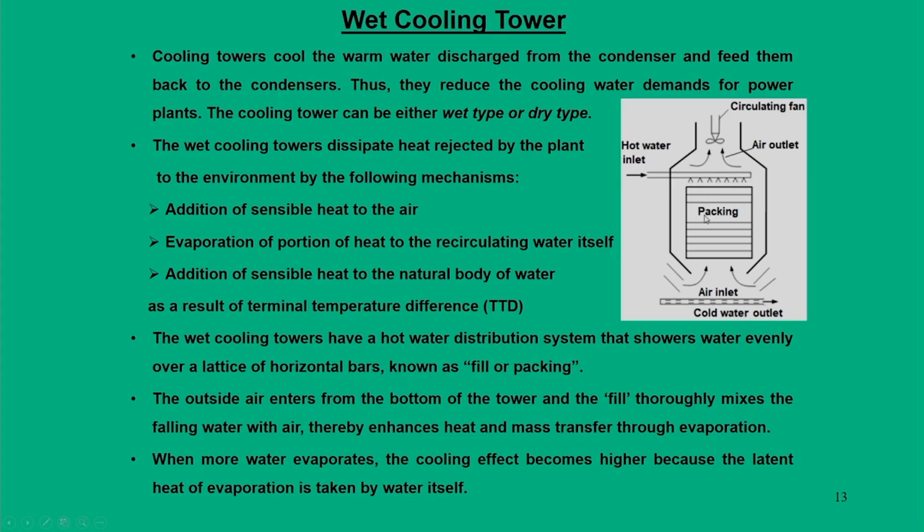That means it is just an arrangement where the entire slug of water gets split through a series of nozzles, and it is allowed to spray through the packing or fill, and from the bottom air gets sucked through this packing.